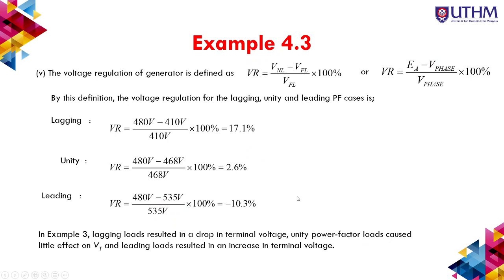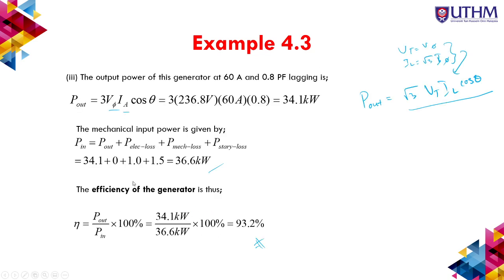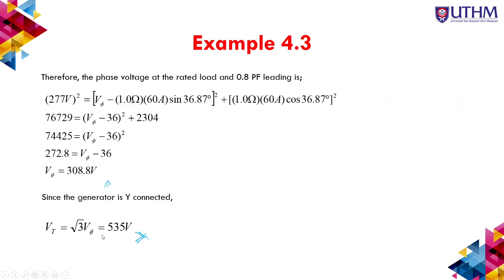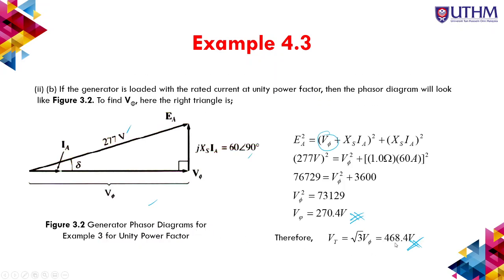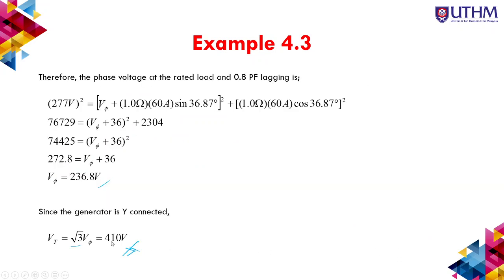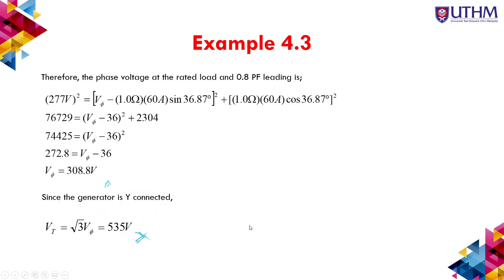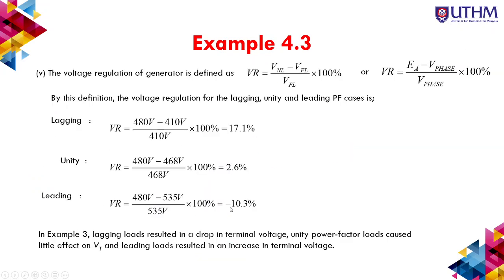Then this is the calculation of the voltage regulation, where we already calculated the voltage. You can see here VT for the lagging, 468 for unity, and 410 for leading. And the V no load is still fixed at 480.